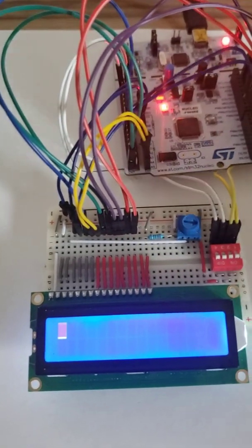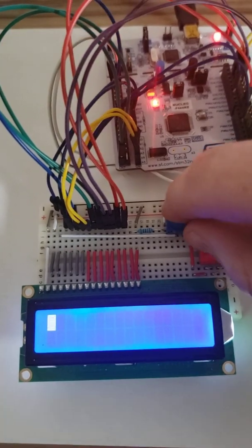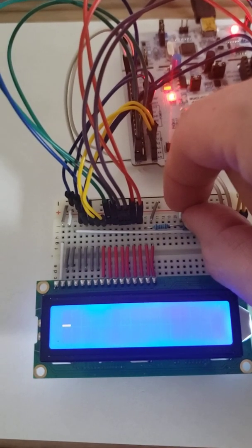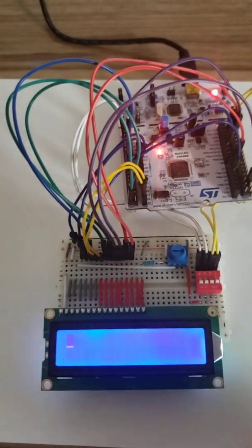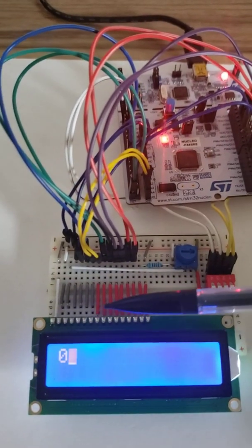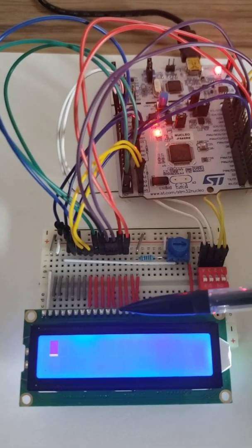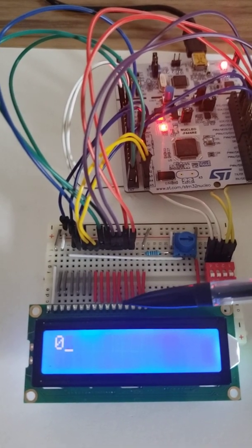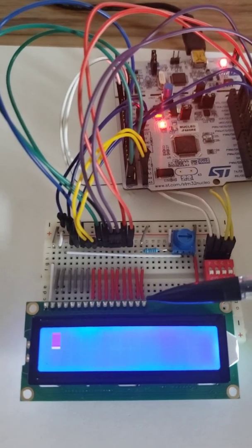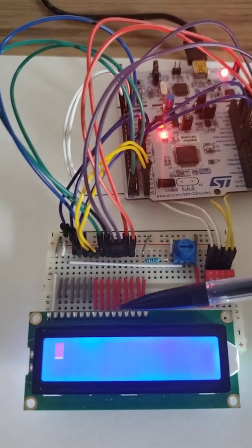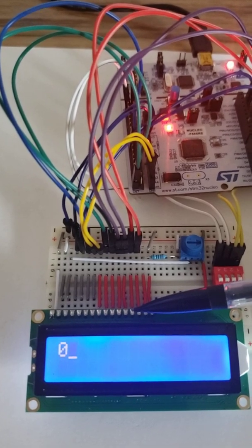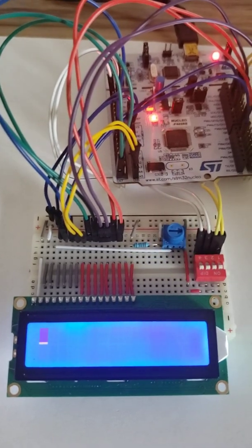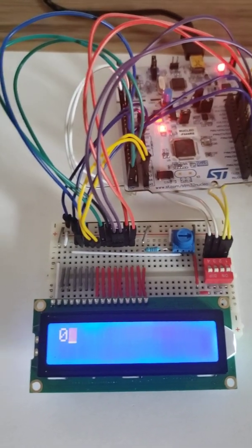We'll reset this back down, and you can see the 10 kilo ohm potentiometer, which individually will adjust your contrast and brightness for the LCD bits. As I said, these additional pins. These are our main pins 1 through 16, and we're going to be mainly using the D0 through D7 pins for the 8-bit operation, and for the 4-bit operation we're going to be using D4 through D7. And then for the 8-bit one, we're using all these pins with the addition of the 4-position dip switch.